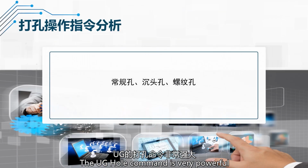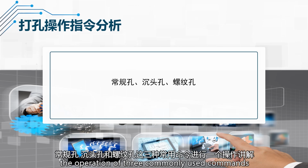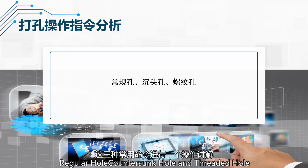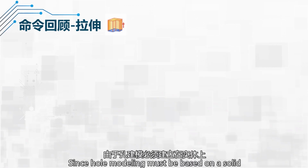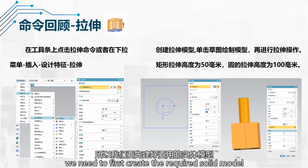The UG hole command is very powerful. This time, we will explain the operation of three commonly used commands: regular hole, countersunk hole, and threaded hole. Since hole modeling must be based on a solid, we need to first create the required solid model.